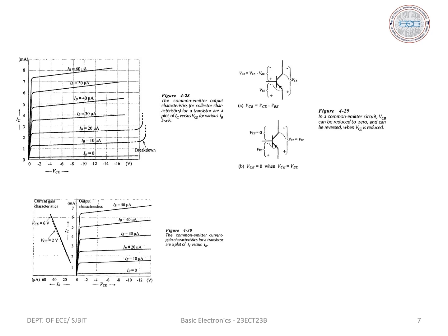Saturation region. The base junction as well as the collector junction must be forward biased to operate the transistor in its saturation region. When the collector to emitter voltage VCE is increased above 0, the collector current IC increases rapidly to a saturation value, depending upon the value of base current. It might be noted that collector current IC reaches a saturation value when VCE is about 0.5 volts. The dynamic output resistance of a transistor in CE configuration is R0 equals delta VCE by delta IC. Cutoff region. In the cutoff region, when base current is 0, collector current is not zero. A small collector current exists, called reverse leakage current.